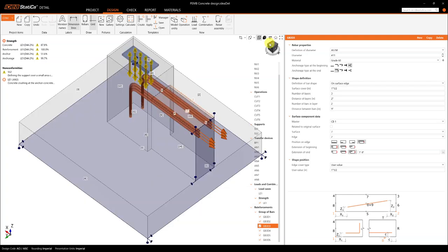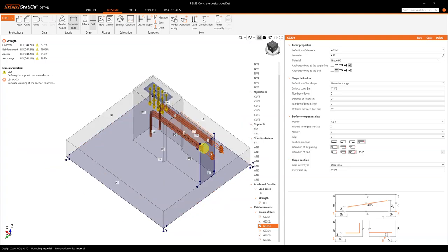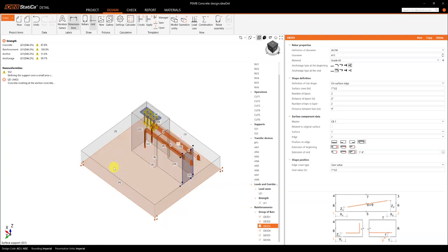At one end, I put this as a continuous because this will continue through this element, let's say, but we are not going to model the entire beam. So by modeling this continuous rebar, it helps us to anchor or make this reinforcement continuous, so it's perfectly anchored to the other side, right?